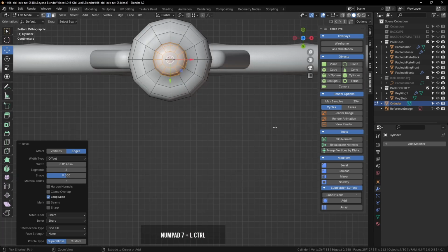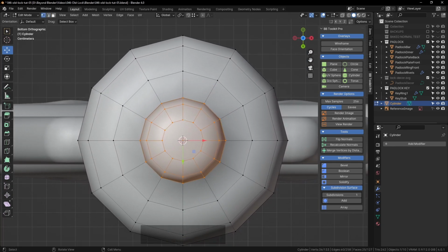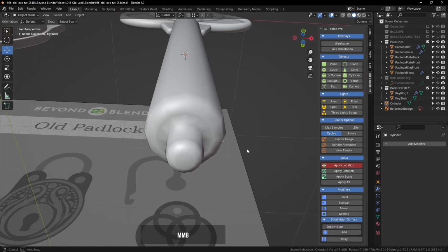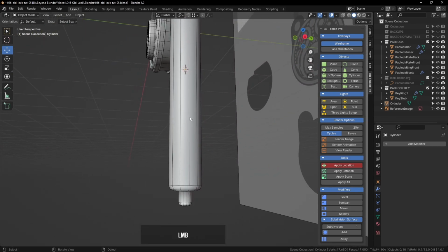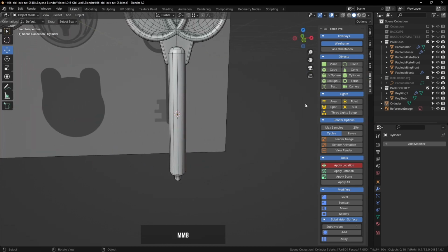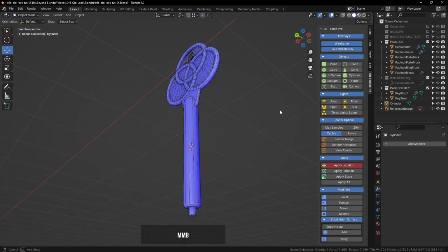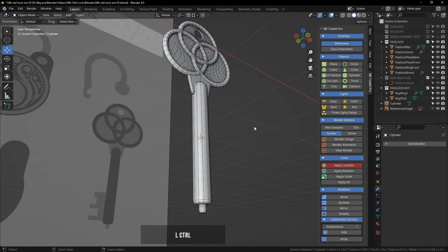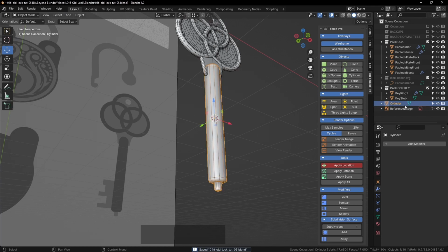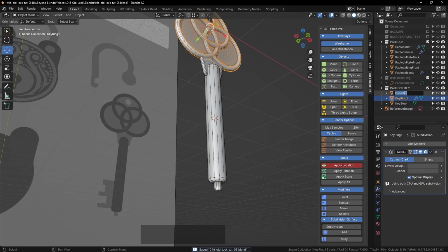And that's good. So that was 7 and Control 7 on the numpad, and that flips the view. And again, I'm just going to join these vertices to create the quads to tidy that part up a little bit. So that's quite easy to do, right? Yeah, let's just do a quick check again on face orientation. I often get caught out with that. So I got into the habit now of checking it quite frequently, because otherwise you end up wasting time trying to figure out why doesn't it work? Why does my texture look weird or my render look odd?